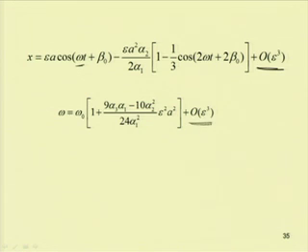So, in this case we have seen this frequency is a function of this amplitude. This equation is similar to that we have obtained in case of the Lindstedt-Poincare technique. In this way one can use the method of multiple scales to solve a nonlinear differential equation.